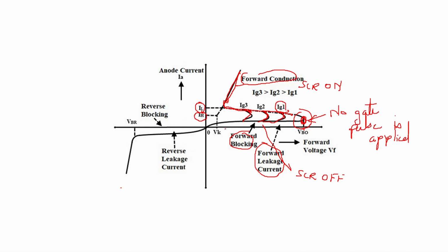And even in the reverse bias, you can see here it is leakage current of the first and third junction, and here once the breakdown voltage is reached, this is reverse breakdown. This is reverse breakdown in which the J1 junction and J3 junction will go into breakdown, whereas the J2 junction is already forward biased, and this kind of breakdown occurs.